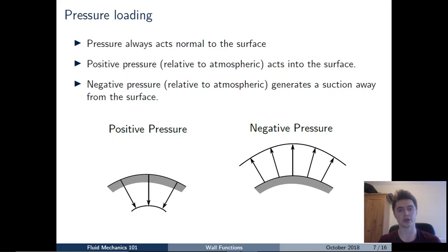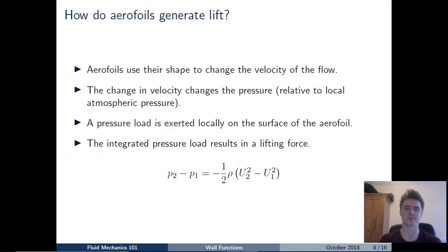So what we're going to do is split the aerofoil and look at the top surface and the bottom surface separately, and we're going to apply Bernoulli's equation along a streamline to understand how the pressure changes along the surface of the aerofoil.